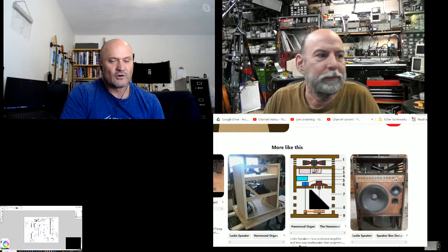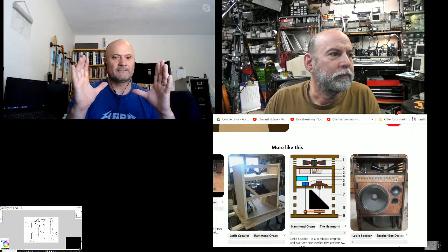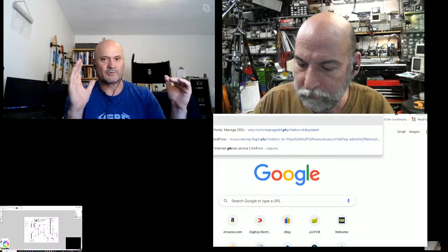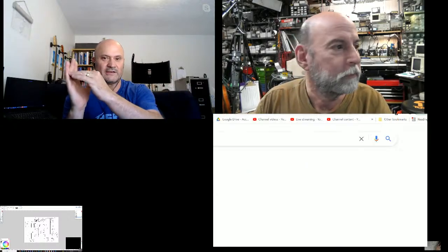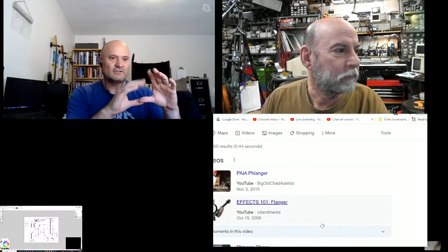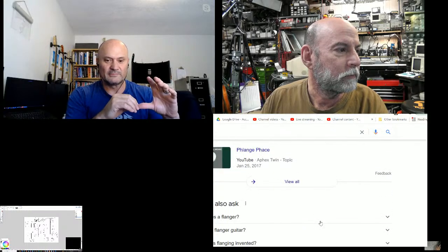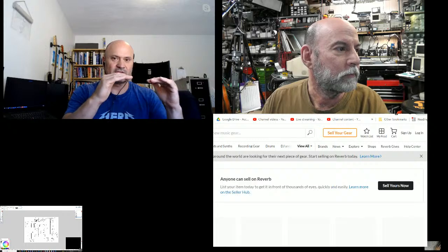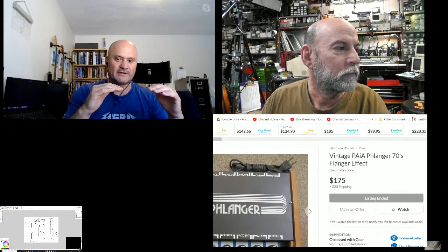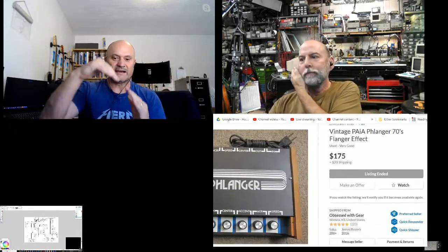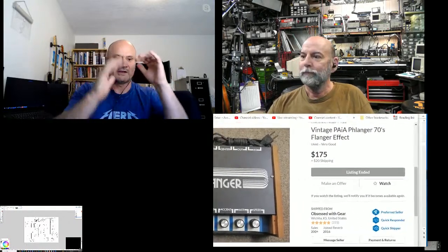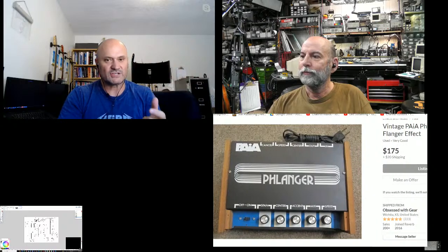So we have a chorus. You take a buffer, it's a circular buffer, so you're putting audio samples into it, and effectively the simplest way to do it is you have a clock that drives your sample rate for the buffer, and you're continuously speeding up the clock and slowing it down, speeding it up and slowing it down, and that gives you the pitch change.